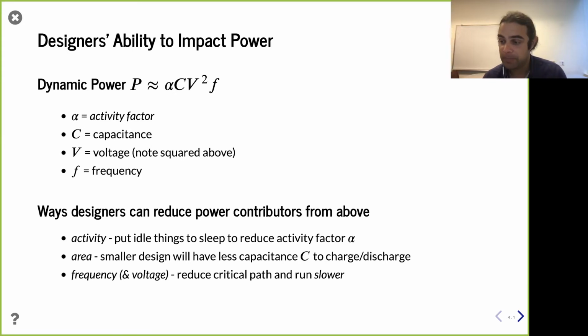If you look inside a processor, interestingly enough, and you try to track the activities and which things have the highest activity factors, sometimes processors have registers counting how many cycles they've been operating. And so that counter is being incremented every single cycle. And so you might say, oh, clearly that counter is going to have a high activity factor.